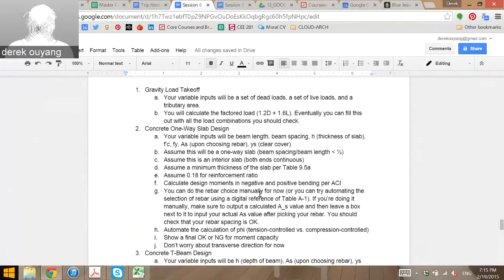But a spreadsheet will plot this for you. And then later on, you'll just say, okay, if I know what moment I'm designing for based on the uniform load on the slab or on the beam, then that's the row I need, given which line I'm looking at here, right? And so that's exactly the kind of thing that, with brute force computational methods, you build yourself a design check or a little slider tool or just a line that will get you really quickly to this without any math.